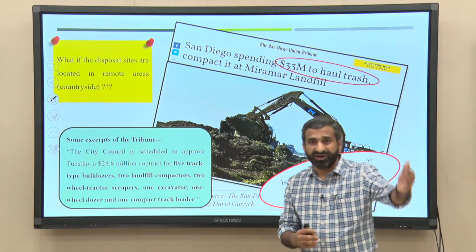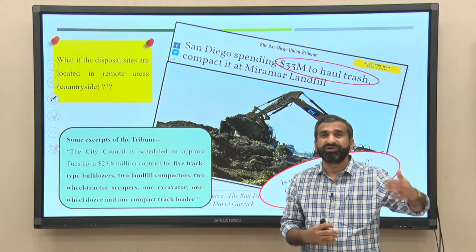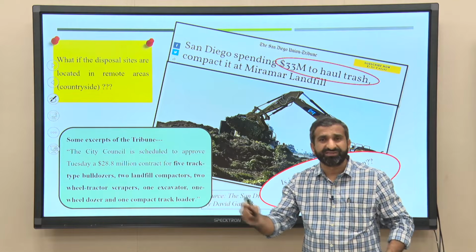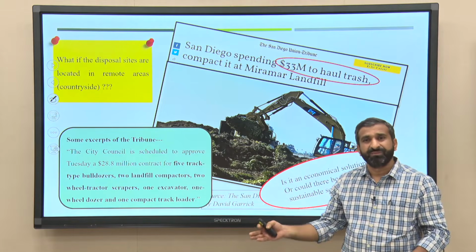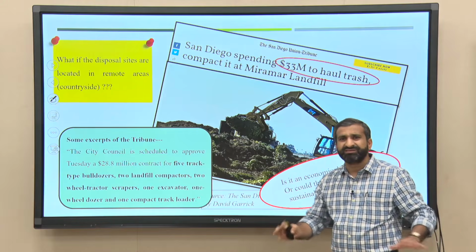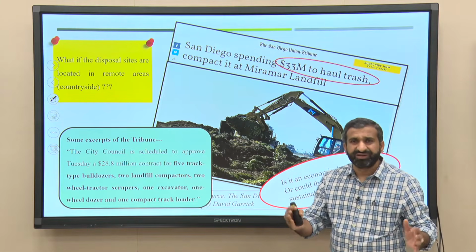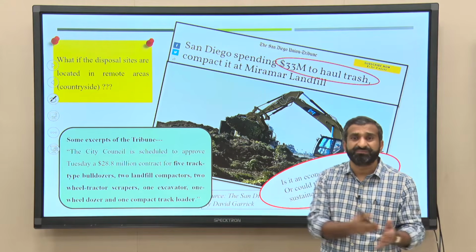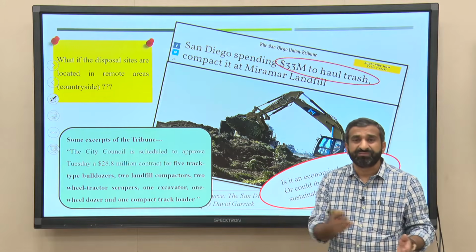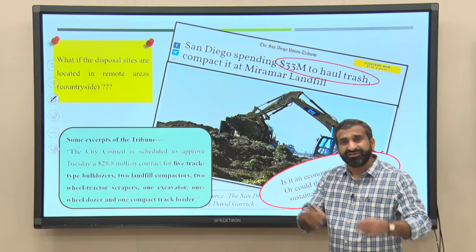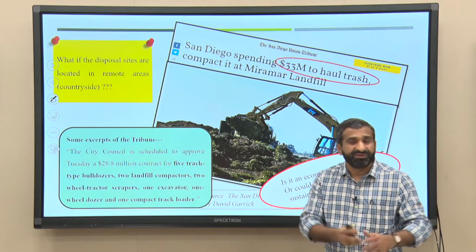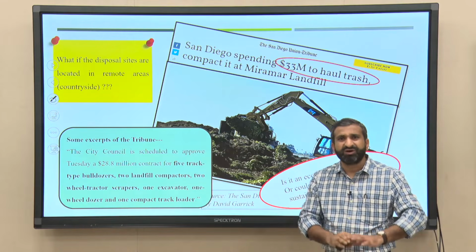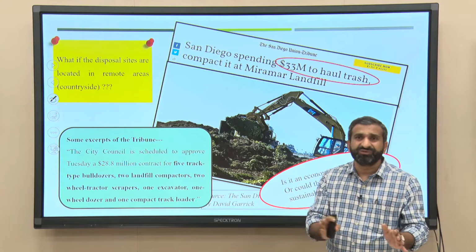So, now they have to go far away. This could be 40 kilometers, 50 kilometers, and with our collection system, whether it is a hauled container system or a stationary container system, except with a compaction facility, it is very difficult to collect more than 2 or 3 tons of waste in a single trip. And if you are planning a hauled container system, having waste of only 2 or 3 tons in a trip means the collection cost will be very high, and because of that the haul collection system is also difficult to accept.